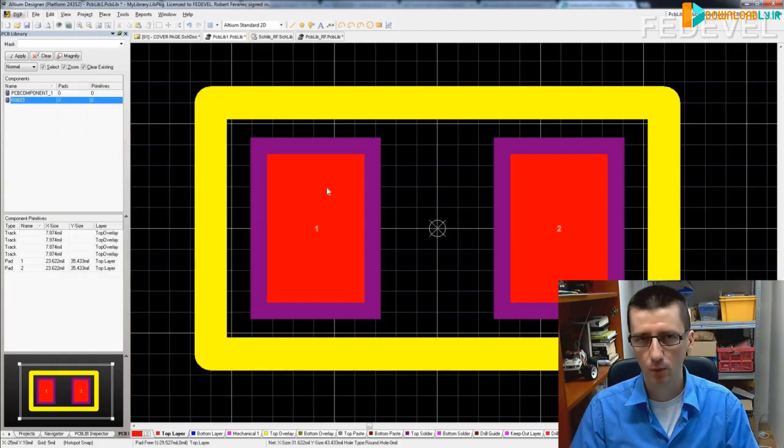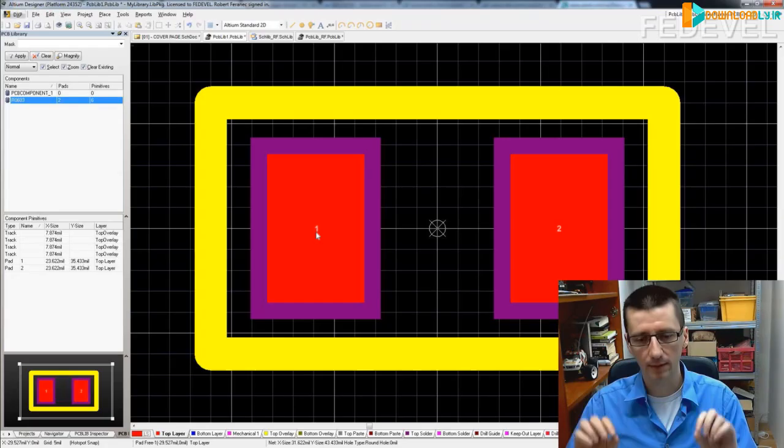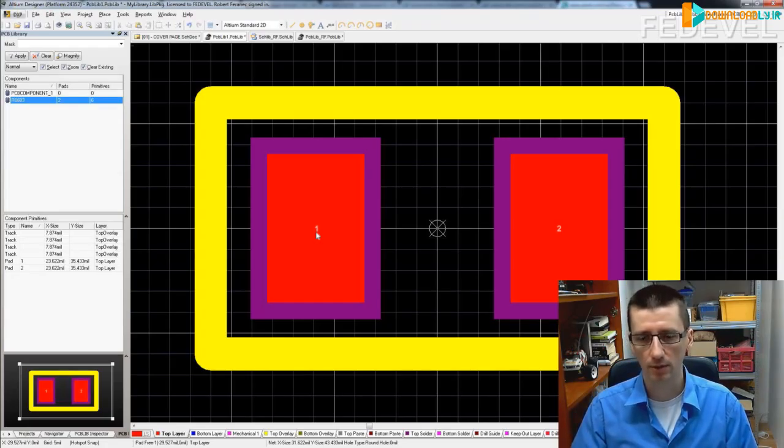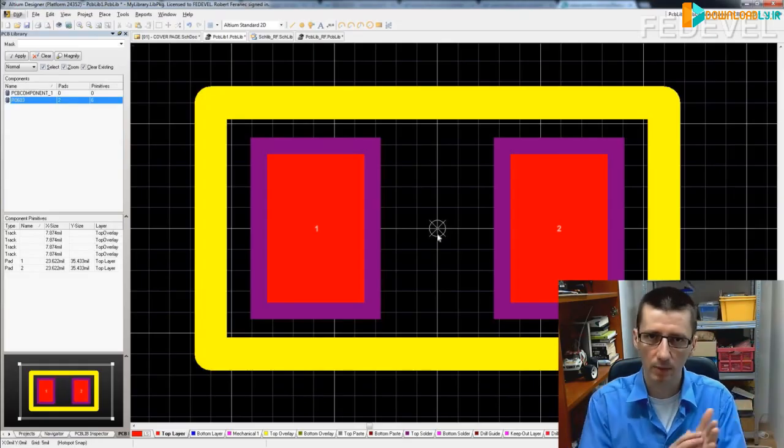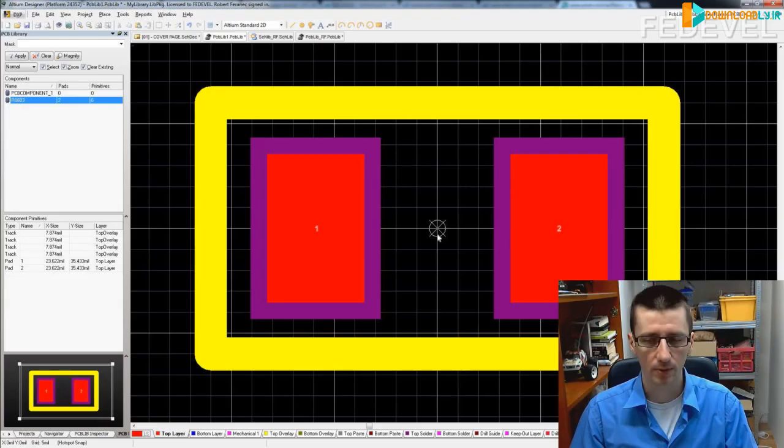For through-hole components which are placed manually, I normally use the reference point in pin 1, because then it's easy to put their dimension on your PCB and tell other people who, for example, design the enclosure. You can tell them where the connector is located, and then they can make a hole in the enclosure exactly based on this dimension. It is easier than if you place it in the middle of the component and pin 1 is somewhere which is very hard to measure.